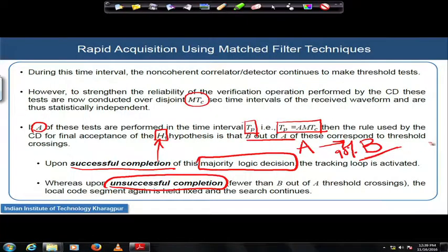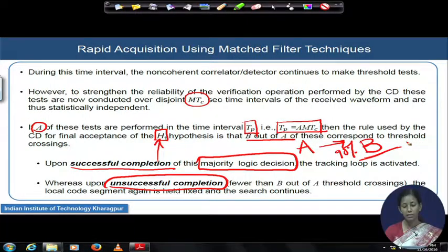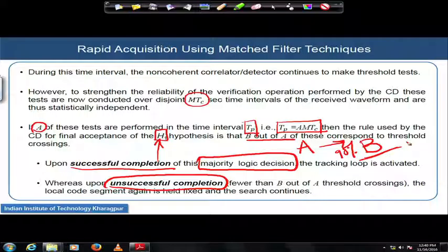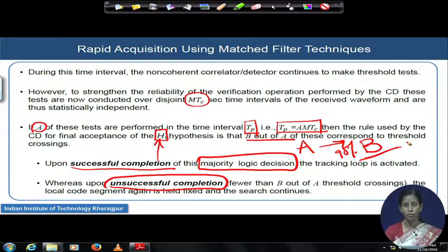So, there is a compromise, a crucial decision you have to take as a system engineer: how good the synchronizer should be and how much time I have in my hand. How strict should I be in taking the decision, how much time should I let elapse, and what final error level of the detected bits am I happy with. It is the level of quality of service in terms of bit error rate, predefined from the customer point and the design point, that leads back to selecting the value of the capital B inside your decision device.